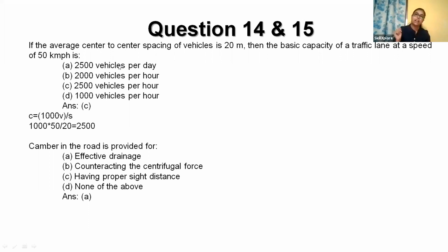And for counteracting the centrifugal force, what is provided? Super elevation is provided to counteract the centrifugal force. Super elevation is also known as cant. So you shouldn't confuse these two words, camber and cant.